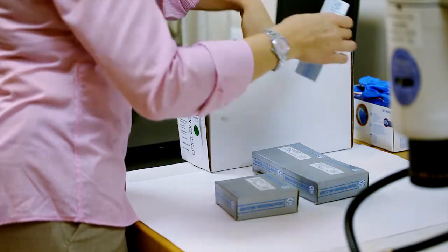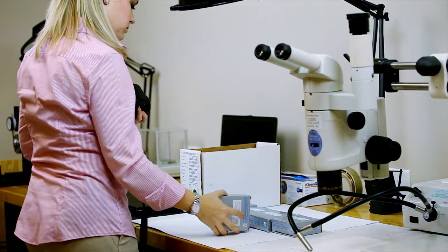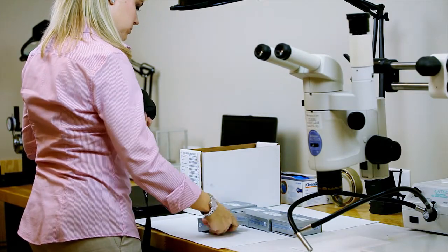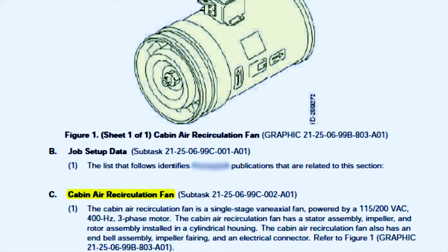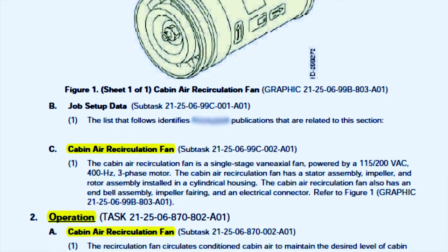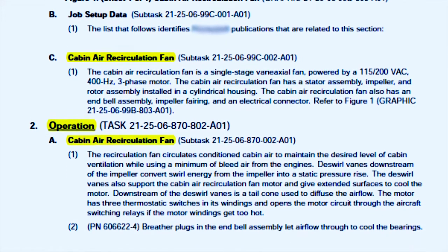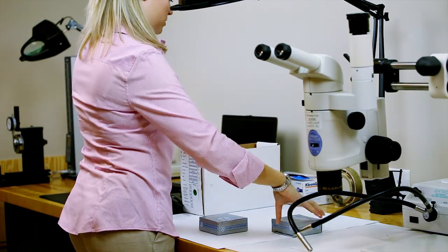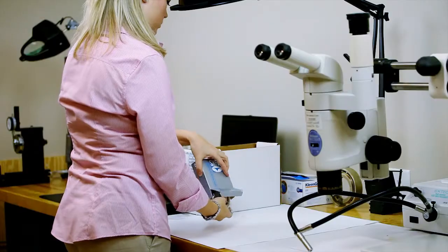Before the project engineer begins reverse engineering, they begin the stage planning by reviewing maintenance manuals and manufacturing catalog information. Maintenance manuals such as CMMs, OHMs, and IPCs are used to help the project engineer understand how their parts fit in specific systems and how those systems function for the aircraft operation. These manuals also provide repair and overhaul information on important part features which can be considered while reverse engineering.